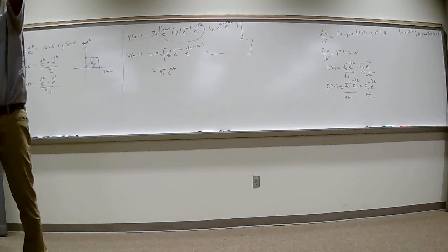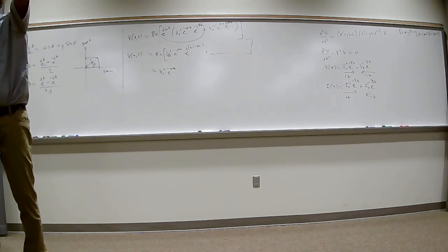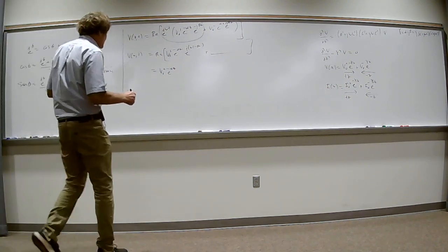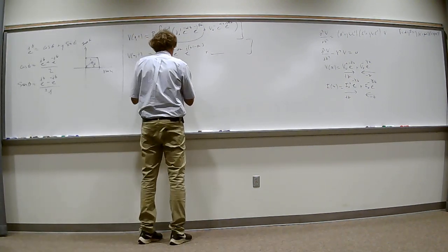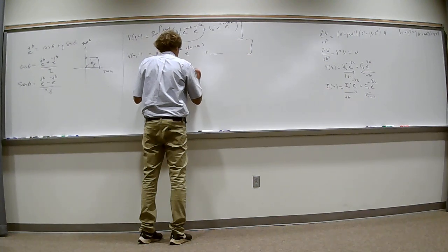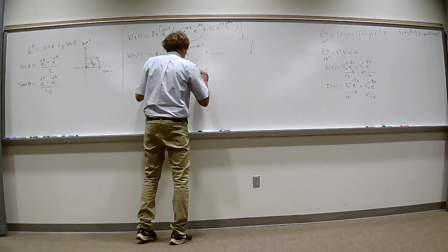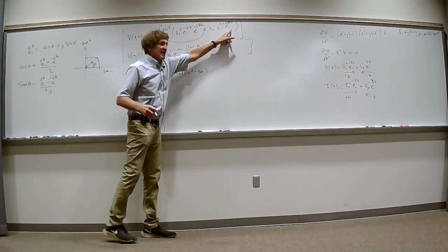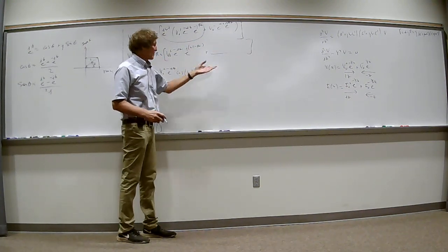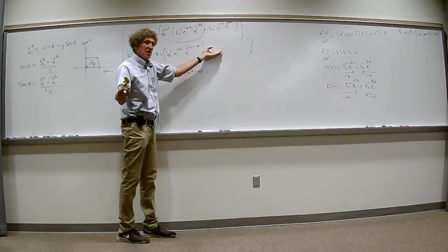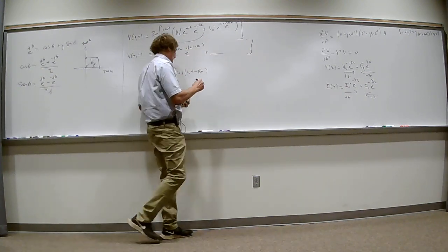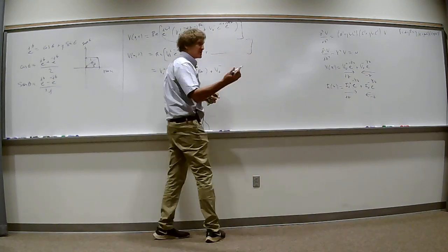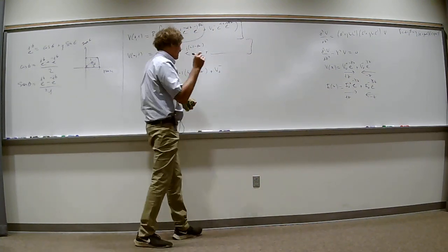Can you all see it in the back? Yeah, all right. I mean, you guys see this and understand it, right? So this is just going to be cosine of omega t minus beta z. We'll get to this in a sec. Now, if I wrote down this, which is the negative traveling wave, here, and multiplied by e to the j omega t, and took the real part, I would get this. The minus indicates it's a wave traveling in the minus direction.